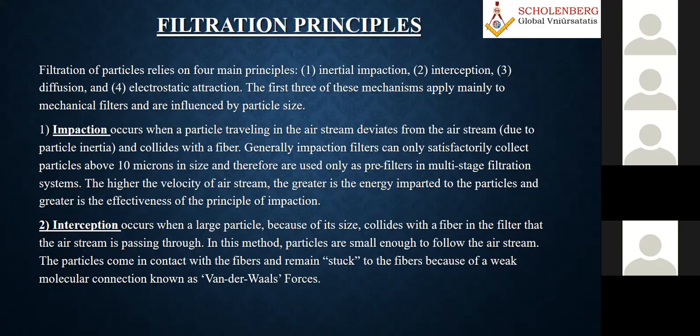Now coming to interception, from the name itself, the large particles, because of their size, collide with the fiber in the filter that the airstream is passing through. In this method, the particles are small enough to follow the airstream. These particles come in contact with the fibers and remain stuck to the fibers because of the weak molecular connection known as van der Waals force. This is a lesser diameter, so it sticks on that.